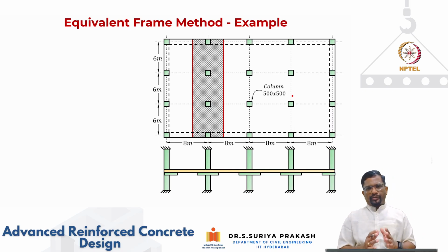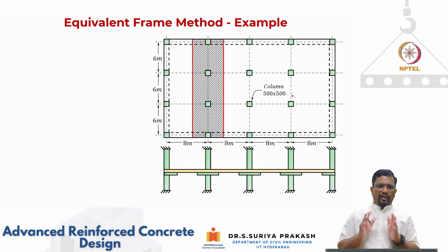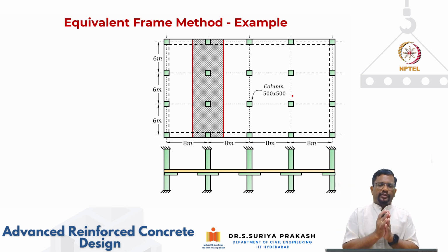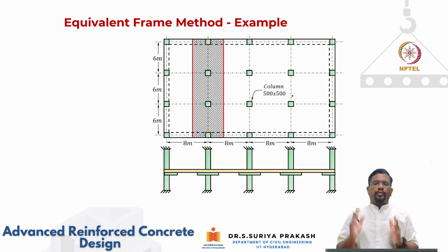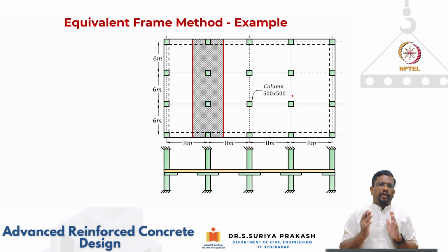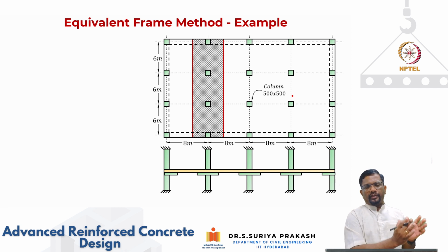So this is the overall procedure. Again, in a nutshell, we are basically doing structural analysis. And in structural analysis, we know the moment distribution method for a regular frame, the prismatic case. Cross sections are not changing. In this case, depending upon the boundary condition, my moment of inertia for the column is going to change. Moment of inertia for the slab beam is going to change depending upon what kind of system I have. Somehow I have to bring these variations into my stiffness parameters, carryover factors and fixed end moments. That is what we have discussed, how to do that.